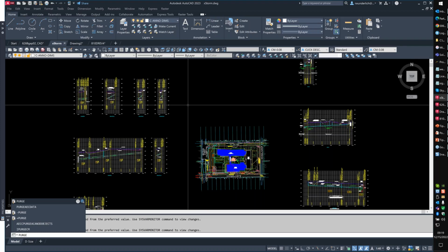It causes that kind of delay because those registered applications, for those of you that don't know, your DWG that gets created is nothing more than actually a very fancy database that AutoCAD is reading. So every time you invoke an action in AutoCAD, like a line, a polyline, a copy command, things like that, it has to go through the database that is your DWG and confirm that nothing has taken precedence or superseded it, which is why it has to go through all of those registered applications and slows down all those processes. It has to validate those before it lets you do the command.